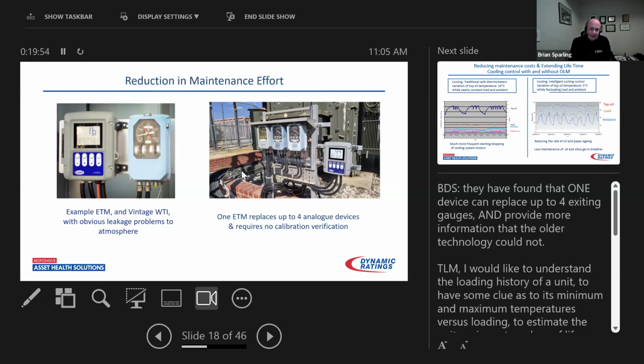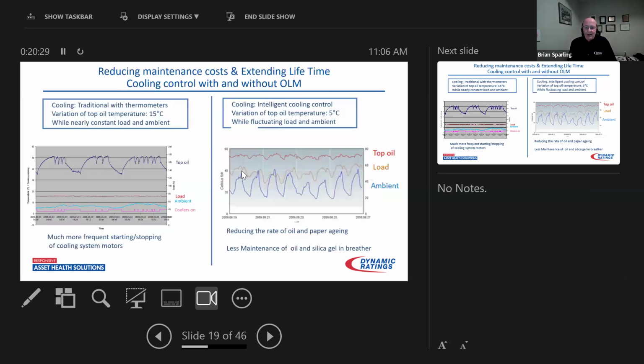With these winding temperature indicators, the vintage types, as I call them, the manuals, when you read them, indicate that the calibration needs to be verified once every 4 or 5 years. It's a maintenance task. When I inform people in the substations of that now, most are completely unaware that that's a task they need to do. The person who had the job before them has retired or by attrition moved away. That knowledge was not shared or passed on.